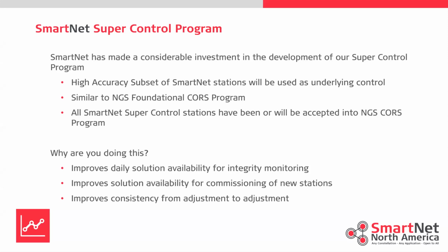Similar to NGS's Foundation CORS program. So NGS is actually working on a Foundation CORS program where they're rolling out stations across the U.S. to be the foundational monumentation and control for the larger CORS network. All of these control stations have been, or will be, accepted into NGS's CORS program or into the NRCan program. So we're going to have NRCan derived coordinates and NGS derived coordinates on these stations so that we can use them in our adjustment. If we can get them accepted by IGS, we will, but that's a big thing.